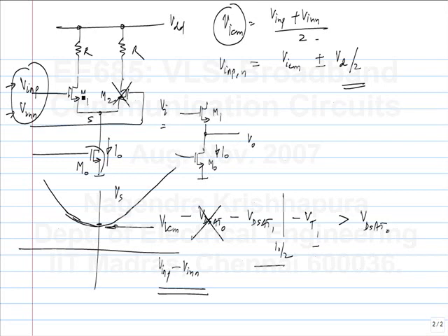So when this is cut off, it follows the voltage of M1. And when this is cut off, it follows the gate voltage of M2. So it does this, and on the other side, it does this. If there is no body effect, this is a line of slope 1. And in the middle, it does something like this. The equation for this curved part, you can derive by writing the square law relationships for M1 and M2. I hope it's easy to convince yourself that it is an even function. It is symmetric, it can't distinguish between Vin P or Vin N.